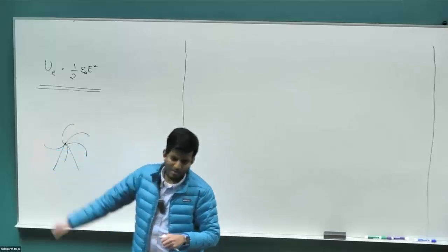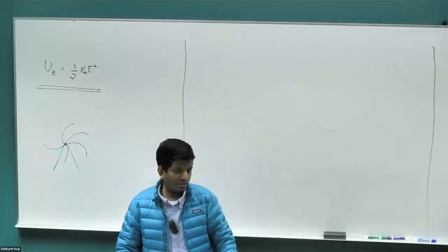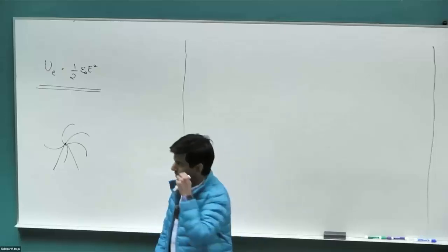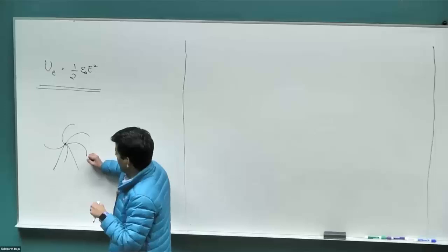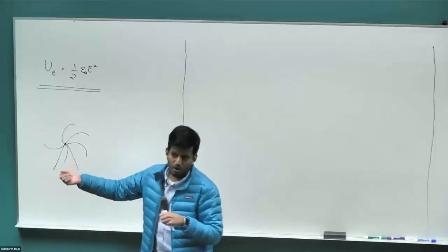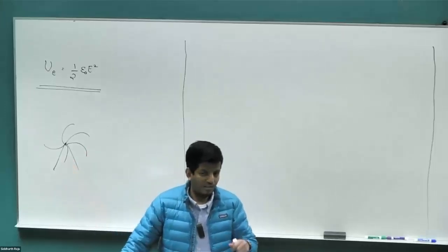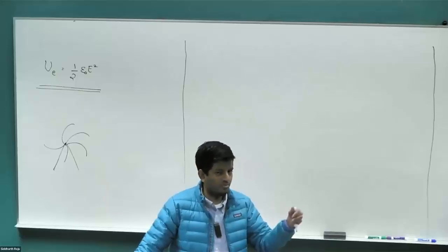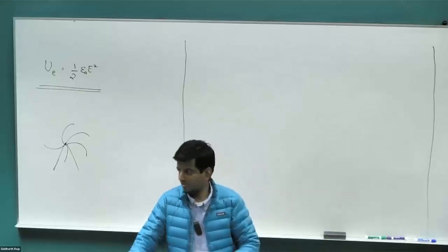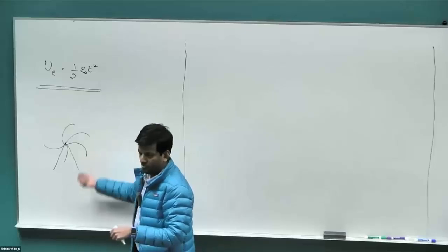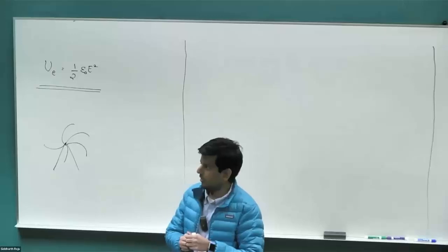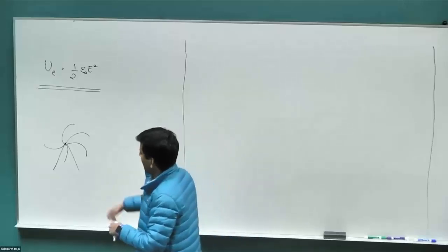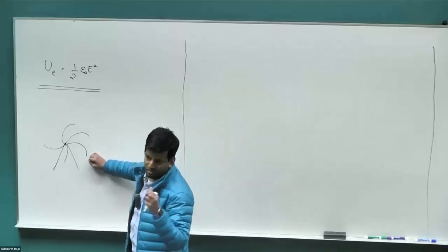push this forward. But this is not particularly a good way to operate a day-to-day motor, because one of the problems is whenever this breaks down, this oxygen is then going to go and react with the metal here and form, if it's copper, copper oxide, which becomes non-conductive. It is not a sustainable way of having a motor which keeps breaking down after a couple of days, right? Because it's constantly getting deteriorated. The metal is being chipped away bit by bit every time that oxidation happens. So whatever electrostatic motor we create would have to operate below the threshold where the air starts to puncture.